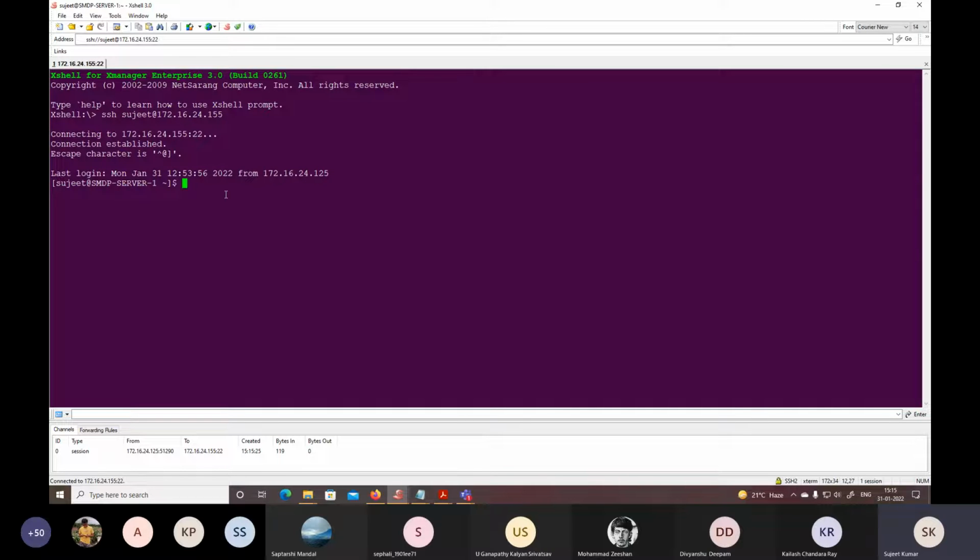The first command is to go to the address where Cadence is installed, or where the cshrc file is installed. So first either you go to that particular folder or you invoke the C shell. So first you write csh to invoke the C shell, and after that you have to change to the working library directory where the cshrc file is available. So we write cd, change directory, cadence underscore ms underscore labs underscore 614. Here our cshrc file is available, in which all the addresses of tools and license are available.